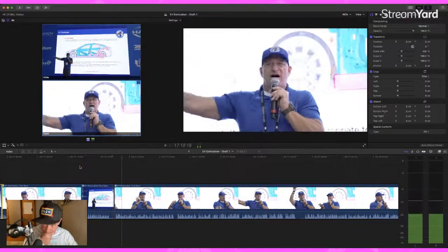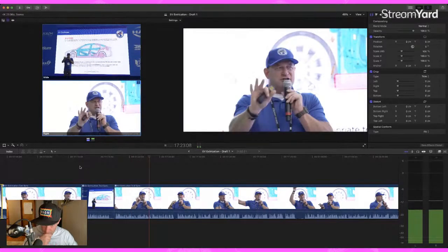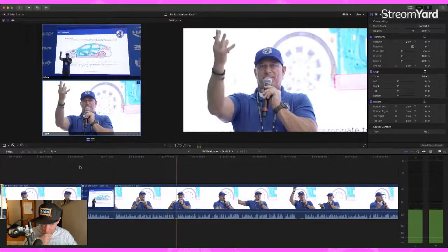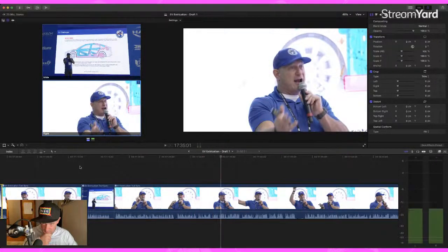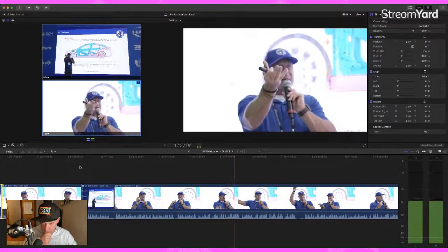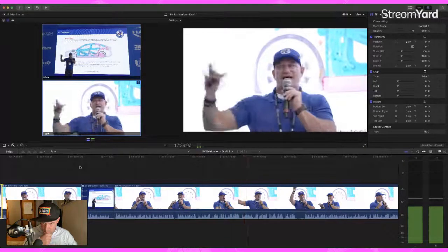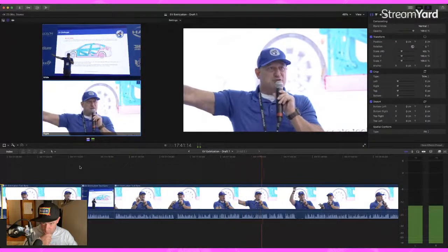When you are initially off-gassing, and everybody please get this, when you're initially off-gassing and the battery system has not created an ignition point and it's not on fire, that is the most hazardous time you can interact with an electric vehicle. So if as first responders you show up, it may look like airbag dust, residual dust from airbag deployment. Assume that that is electric vehicle potential thermal runaway.